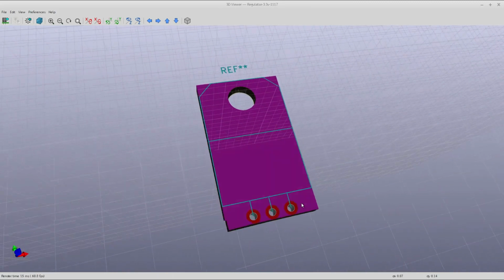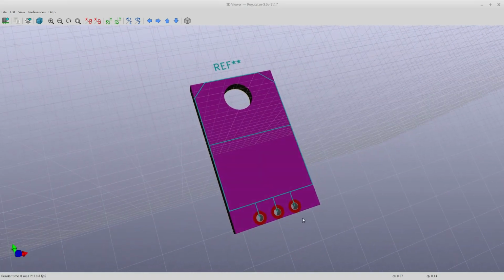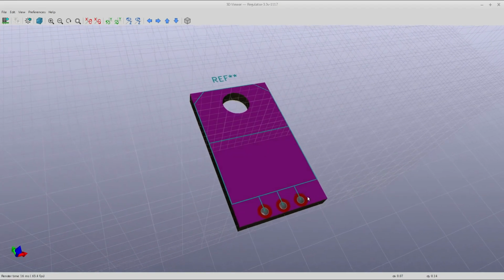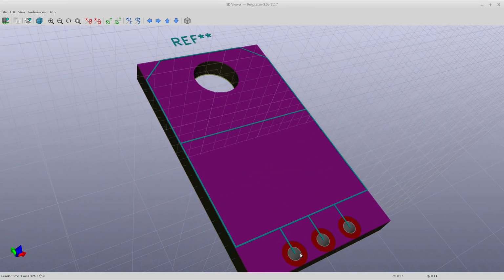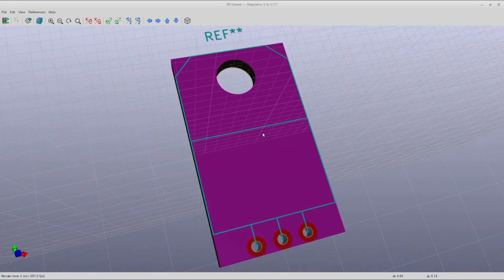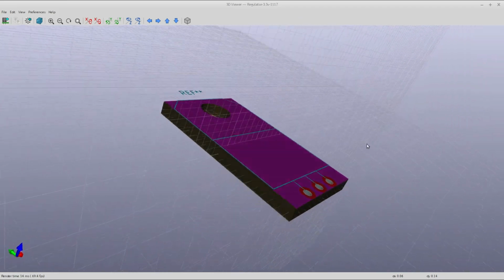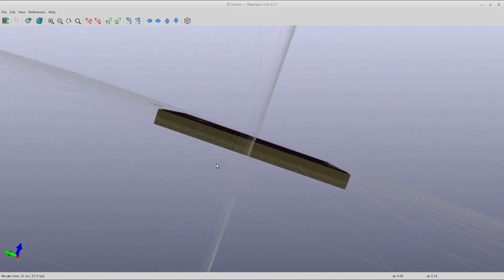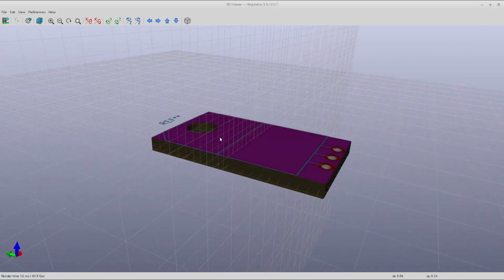Now if you roll this around, as you can see, it took what we did in a previous video about making that footprint, and it has the silkscreen trace on here, it has the copper pads you can see in red down here, and the holes that do go through here and up here. The big obvious thing that's missing is the actual component itself. If you're going to put this into a box and trying to eke out all the space possible, you might want to know how tall the component is before you just go building a case up and hoping.